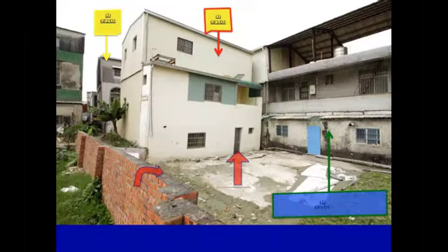Here now is a view from the southeast region of that last mapped image, looking into several buildings where clear evidence of liquefaction in the field is noted by bulging of the exterior slabs, and evidence of rotation of screen fences and surface boils and the like. The pair of buildings on the left of this image observed ground failure features at their exterior classified as moderate to severe, GF2 to GF3, while the resulting structural damage was graded as heavy. You can't see it from this viewpoint, but each of these has significant discontinuities and structural damage of their supporting structural elements at the base as viewed from the inside of this alleyway.